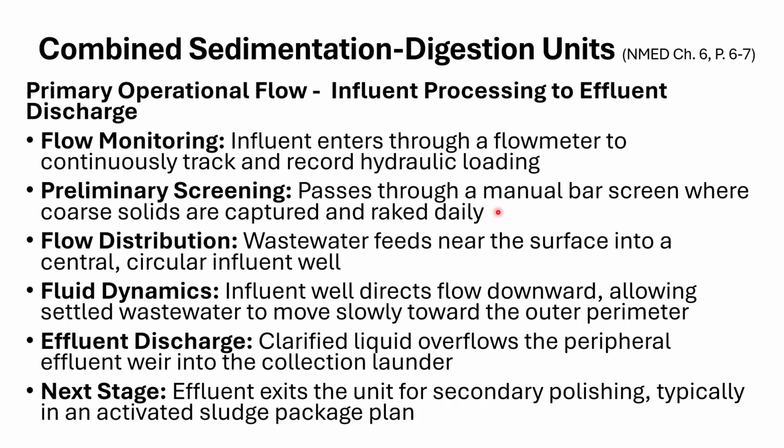Okay. The first thing that's going to happen is the preliminary screening, the preliminary treatment. You're going to have a bar screen there, and those branches, diapers, wipes, what have you, are going to get captured so they don't go inside that basin or clarifier and create a problem for your process. That's going to be captured, raked up, and disposed of. It's raked out daily to make sure that screen's kept clean, and then it's all taken to the landfill.